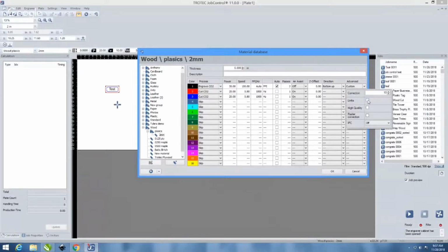If you've ever done rubber and didn't use this feature, you'll find you had to clean each individual stamp die by hand with a toothbrush. It's very inconvenient and very cumbersome. If you use the links feature, it allows you to engrave an entire sheet of rubber stamps and then clean the whole sheet all at once. So you can clean an entire A4 size sheet of rubber in a matter of 3 or 4 minutes versus taking probably half an hour. It's a massive time savings.